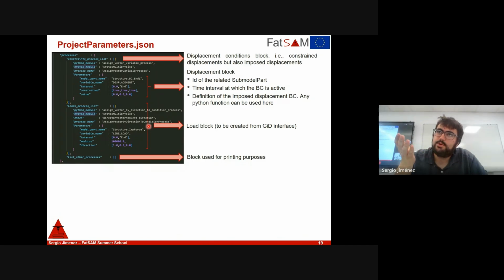While if you impose displacements in your model, then convergence can be reached, even during the softening phase, okay? So usually I will not recommend you to use forces while running nonlinear simulations, unless you use other techniques like the arc length algorithm and so on, that are also available in Kratos.